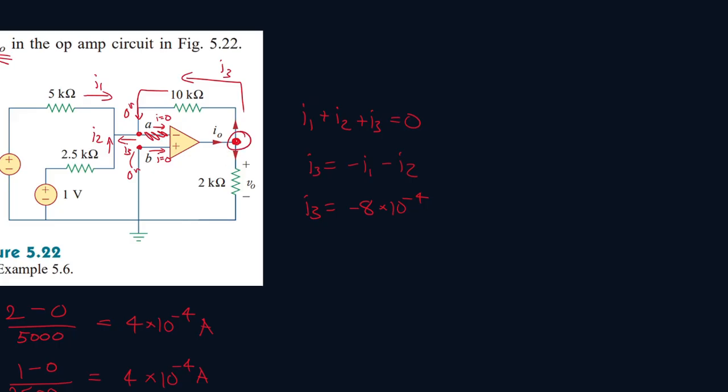So the voltage here will actually be VO, because if our current goes down this way, since it leaves from the negative terminal, it must drop by VO and equal 0 volts as we hit the ground. So VO minus VO will give you 0 volts. So that means this region will be VO.